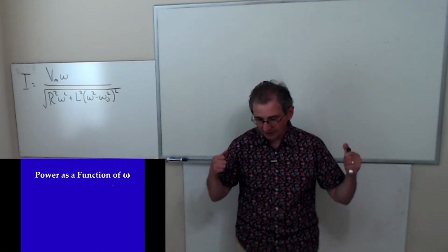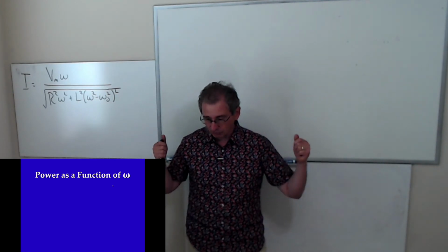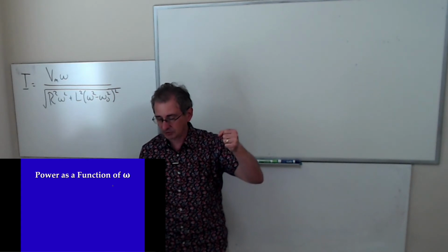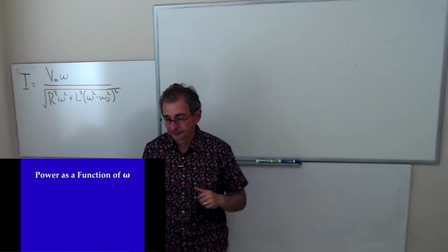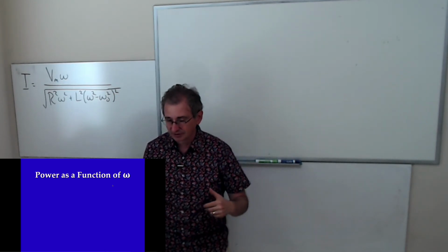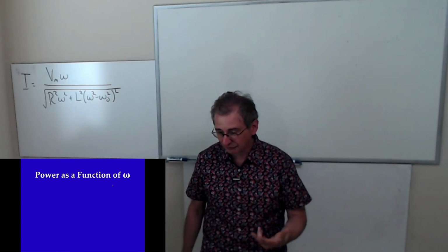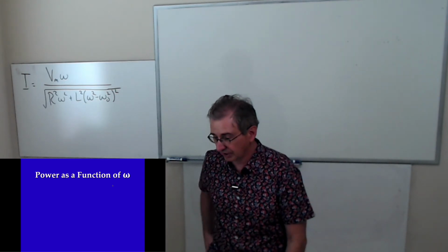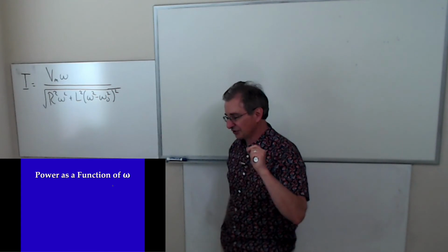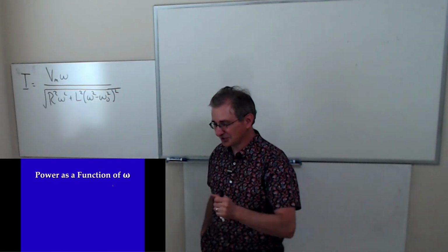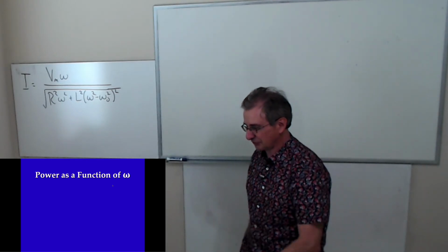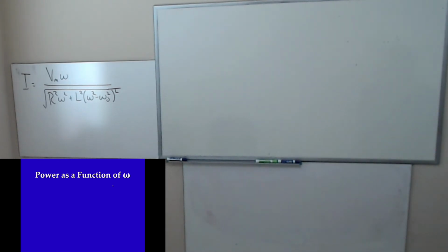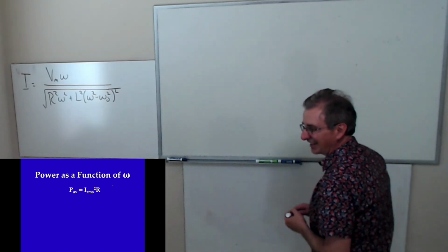So you'll see somebody, you need a special power supply for this, run the signal generator at 120 volts, hold the light bulb in their hand, light bulb goes on. They don't feel anything. They run at 100,000 hertz. This is the skin effect. High frequency signals won't go very far into your skin. And as a junior level person in physics, you can solve that problem and derive the expression for what's called the skin depth. But we won't deal with that here.